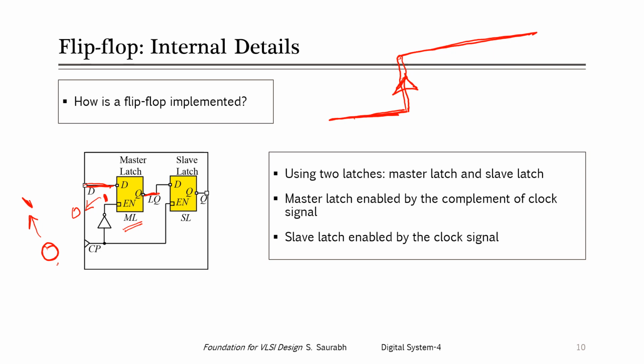And the second thing is that the slave latch now becomes transparent, right? So whatever was last latched at this particular point when the edge came will be available at the Q pin of this slave latch. Note that the input is now not changing for the slave latch, and therefore it will remain stable.